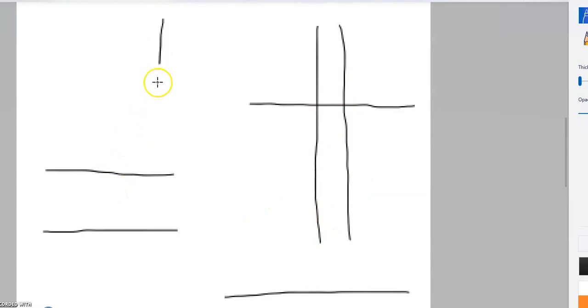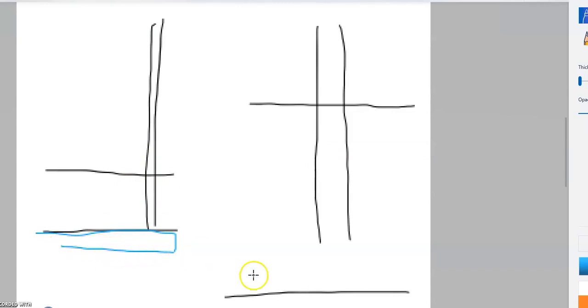But here, if we drill a vertical well, we won't get more area with the formation, and the problem will be bigger if we have an aquifer here and a gas formation or gas cap at the top of the formation. So coning problem will happen faster.